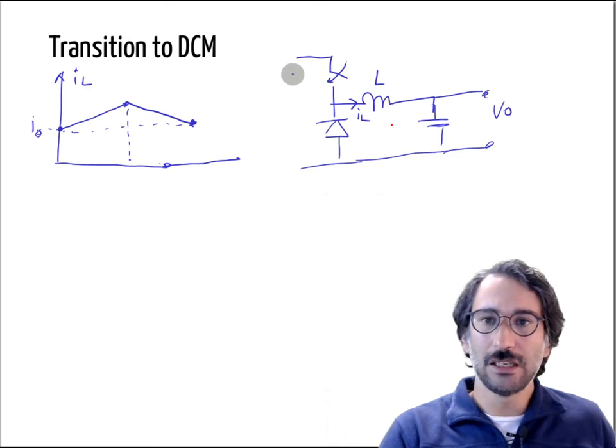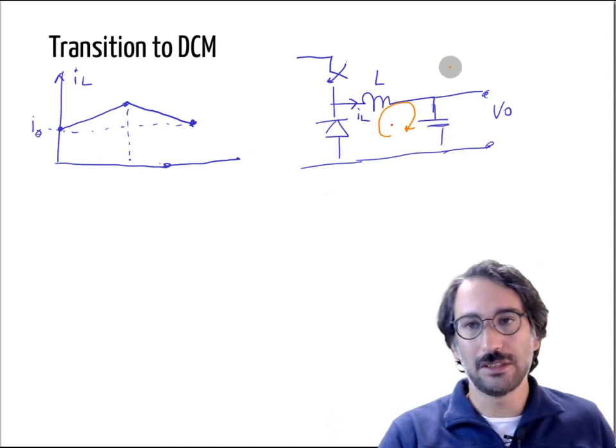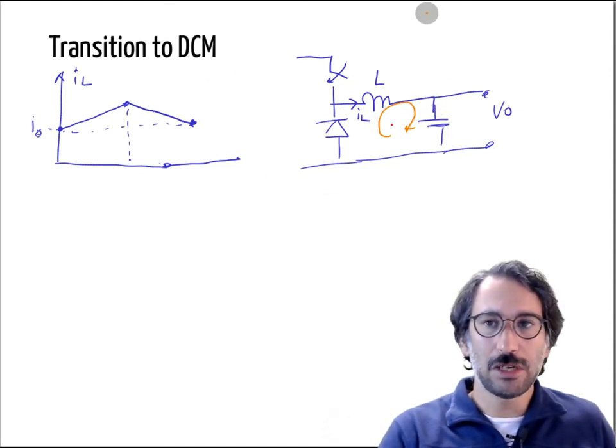So basically you are transferring some energy from the source side to the inductor, and in the second half, while the inductor is discharging, it is still charging your capacitor. So the power flow in the second cycle is from your inductor to your capacitor, and from your capacitor to your load. Anyway, so what would happen?